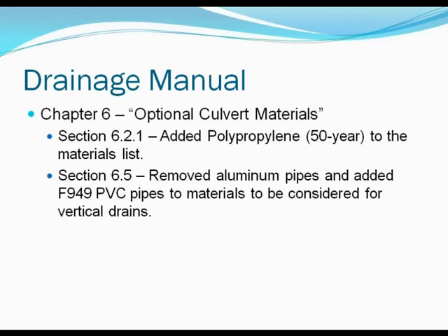The polypropylene pipe is a little stiffer than polyethylene, a little less stress crack resistant, a little more susceptible to, in fact, significantly more susceptible to oxidation. Right now, it's 50 years. The industry has presented evidence of defensible oxidation protection, antioxidant formulas. We anticipate that will eventually go 100-year, but it will be with more rigorous testing. So that's an option that's come on board.